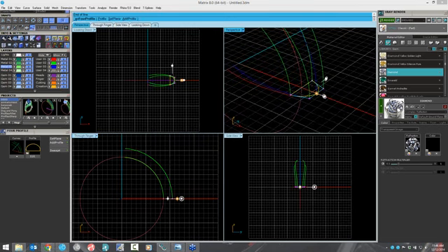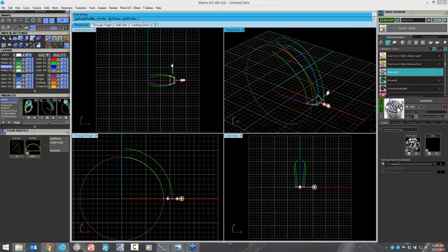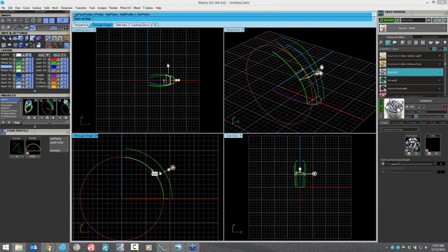If you want another profile, just like our other profile builder, you hit Add Profile. It adds it right where it was, and you can move it. You can rotate it. If you know exactly where you want it, you can come over and say Set Plane, and you can draw like so and set it.